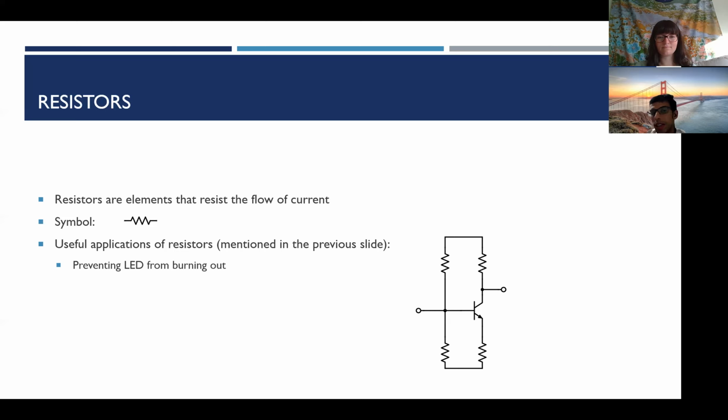The signal is just added on to those 0.7 volts, and it's usually much smaller in amplitude than 0.7 volts. So the signal comes in here and exits amplified here, and all these 4 resistors are basically playing a role in biasing the transistor correctly. This resistor at the top right is governing how much the signal is going to be amplified. So that's yet another application of resistors.